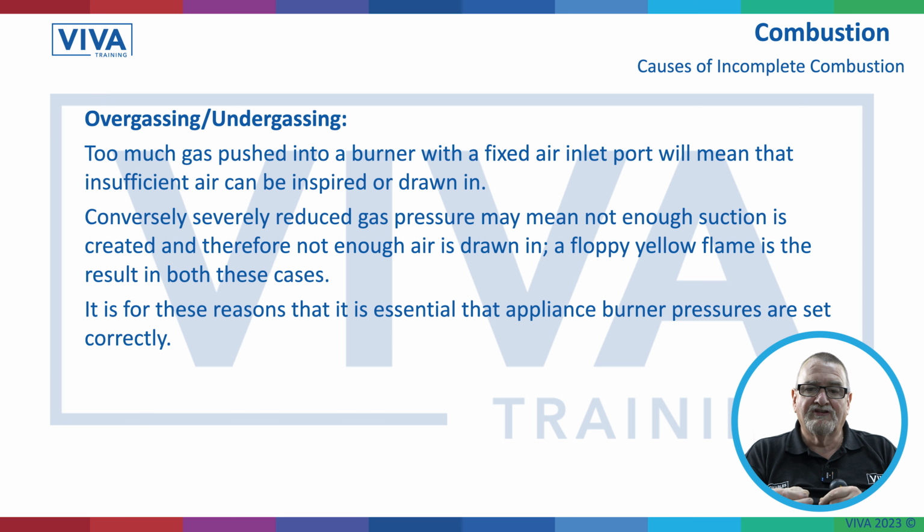Conversely, with severely reduced gas pressure, there's not enough suction. As the gas goes through what's called an injector, and we're going to look at these things further on in future presentations and slides, the gas goes through an injector, and in going through there, it starts to drag the air in with it. Now, if there's not enough pressure, it doesn't drag enough air in, so again, we don't get that nice air-gas mixture. So it's for those reasons it's essential that appliances are set up and the pressures are set correctly.